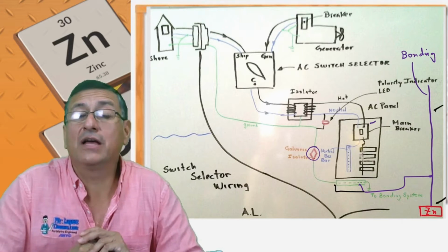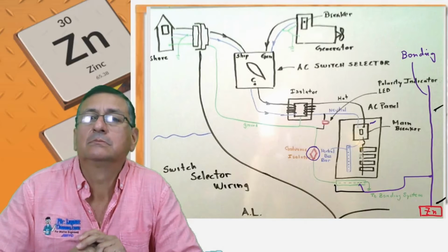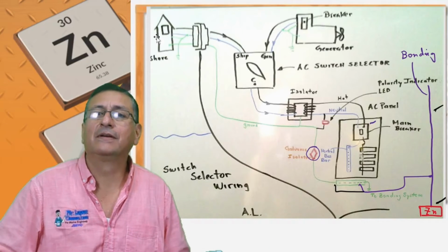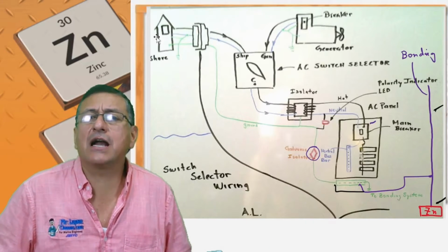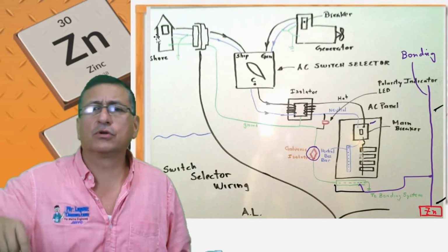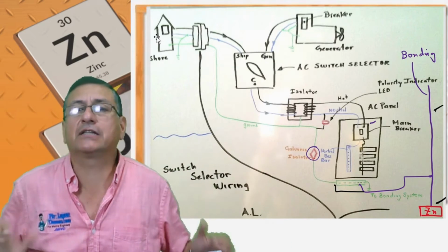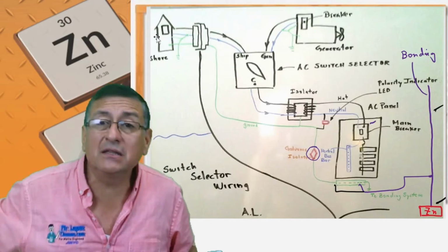Remember, the ground bus bar is connected with the bonding, and the bonding with the sink. Right now in the bonding, you have 120 volts constantly. What elements are connected to the bonding? Through holes, the block of the motors, cabinets, fuel tanks, everything is connected to the bonding. And now the bonding is hot.